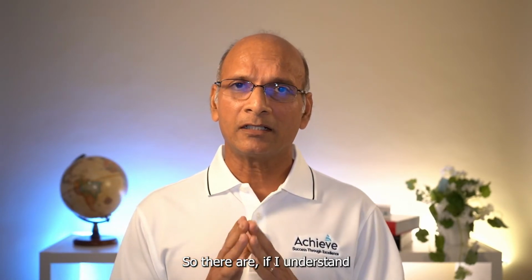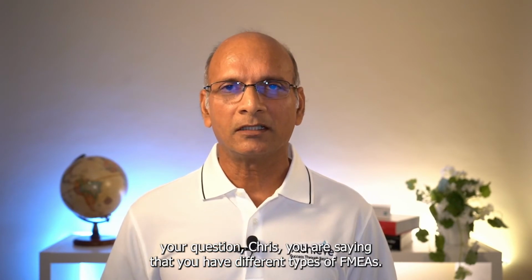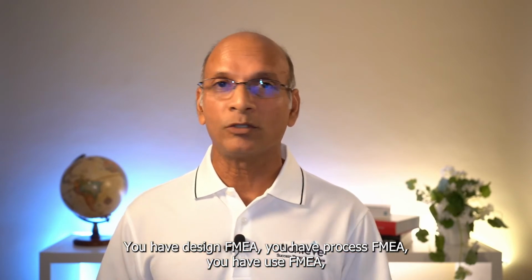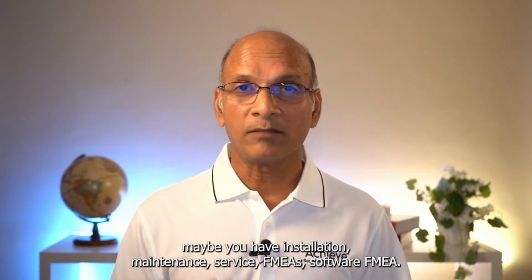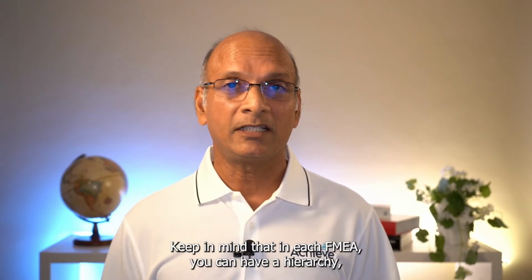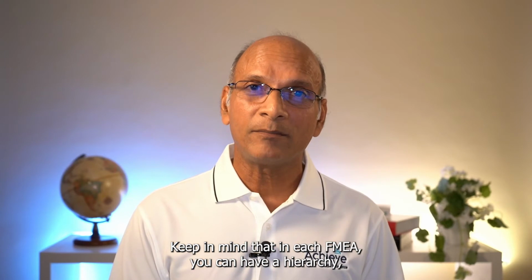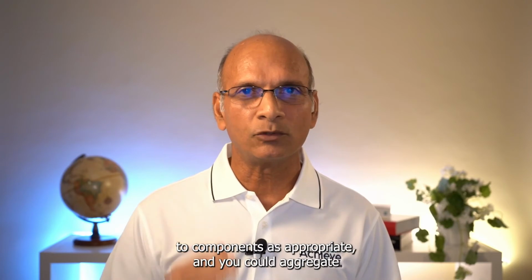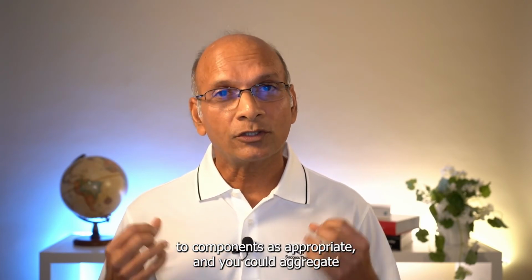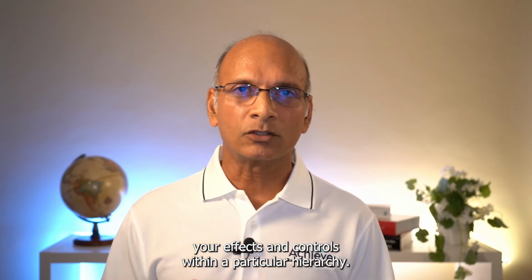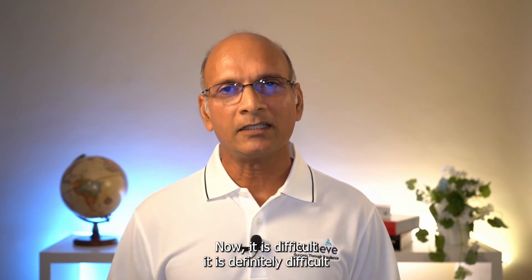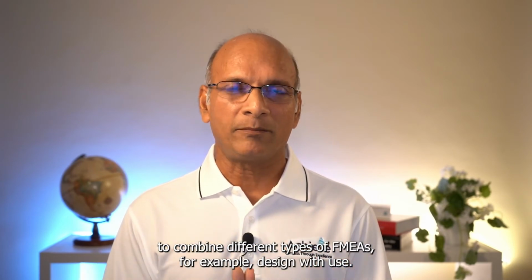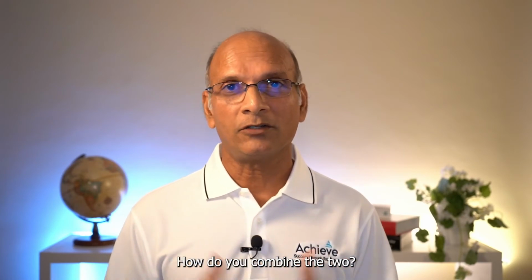So if I understand your question, Chris, you are saying that you have different types of FMEAs. You have design FMEA, you have process FMEA, you have use FMEA, maybe you have installation, maintenance, service FMEAs, software FMEAs. Keep in mind that in each FMEA, you can have a hierarchy. You can have a hierarchy going from system to subsystem to components as appropriate. And you could aggregate your effects and controls within a particular hierarchy. Now, it is definitely difficult to combine different types of FMEAs. For example, design with use. How do you combine the two?